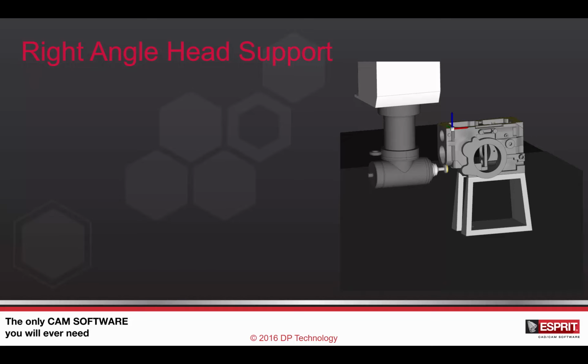So you might encounter this in heavy machining, perhaps a machine like the Mazak FJV, which is capable of doing 5-sided machining, but actually doesn't have a rotary axis on the machine. The way they can achieve this is by having interchangeable heads. And when they attach the right-angled head, they can rotate that head around the tool spindle axis to be able to machine the 4 sides of the part. We're going to take a look at that example in just a minute.